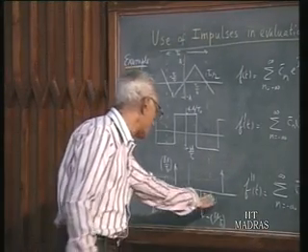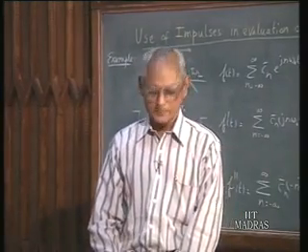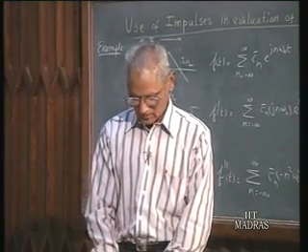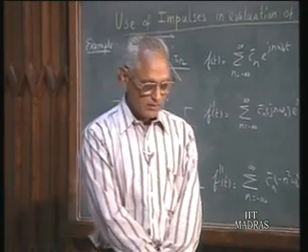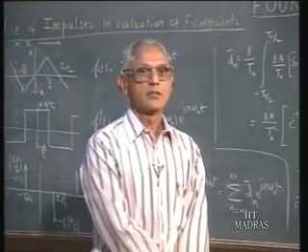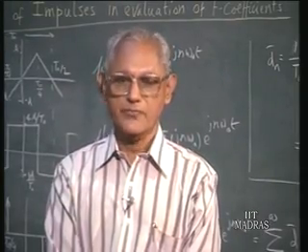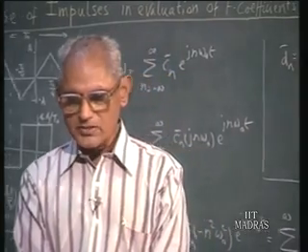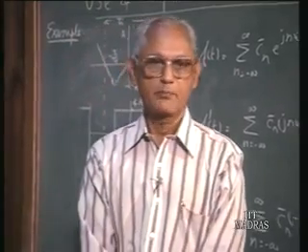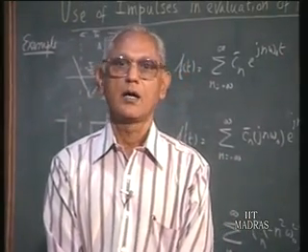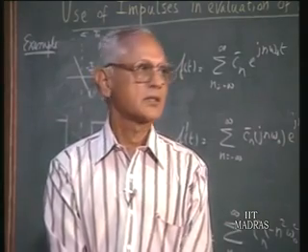as illustrated here. So in this lecture, what we have done is we have introduced ourselves to the concept of frequency spectra, in particular the magnitude and phase spectra associated with the Cn coefficients. We observed that these both are line spectra. The magnitude spectrum is an even function of n, and this phase spectrum is an odd function of n. And we have, through a series of examples, seen how the spectra can be constructed. In particular, we have constructed the spectra of a train of impulses, the square wave, and a train of pulses.